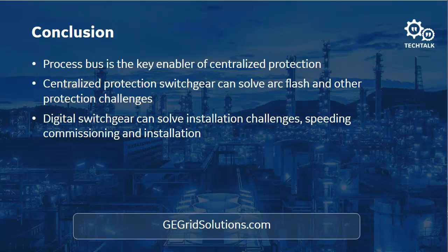Now, as it turns out, 4 to 5 milliseconds is a typical time for a mechanical output to operate on a relay. So if you replace that mechanical output on the merging unit with a high-speed output, so this would be an electronic output, those are available on the MU320 now as an option. If you do that, you get back that 4 milliseconds. And so you come back to about the same sort of performance with the high-speed outputs as you would with a traditional relay with a mechanical output.